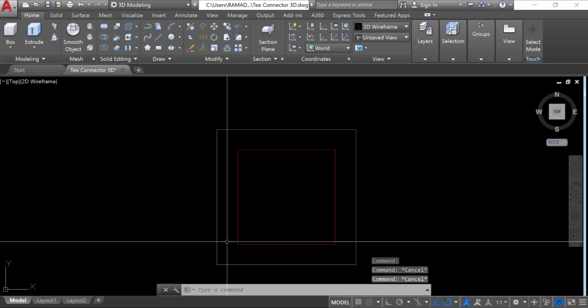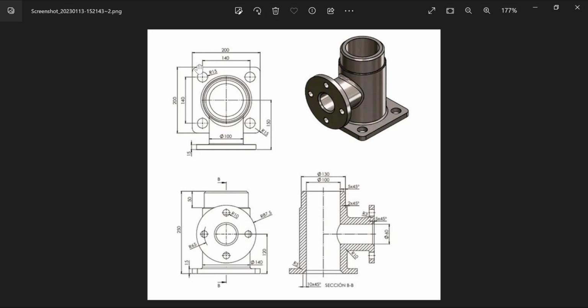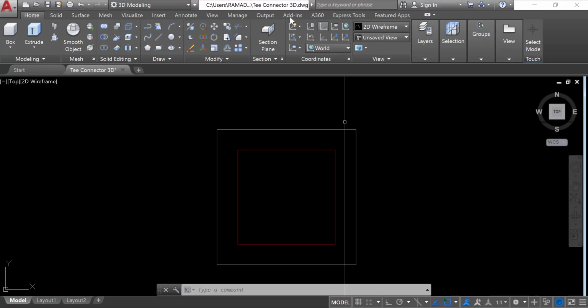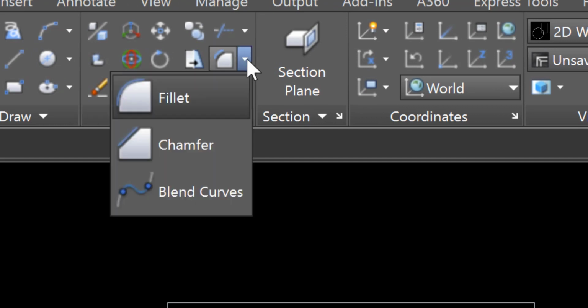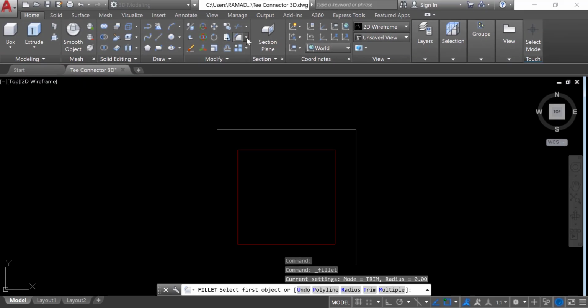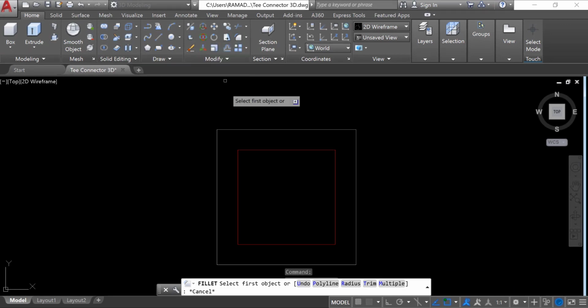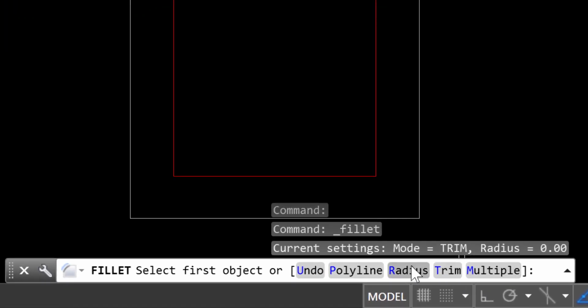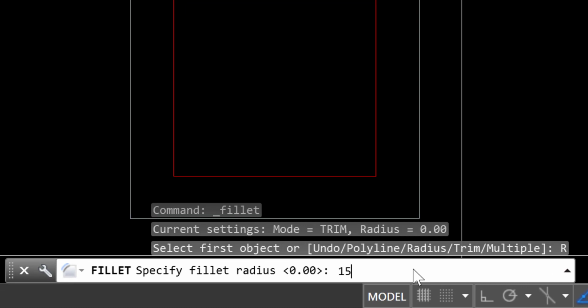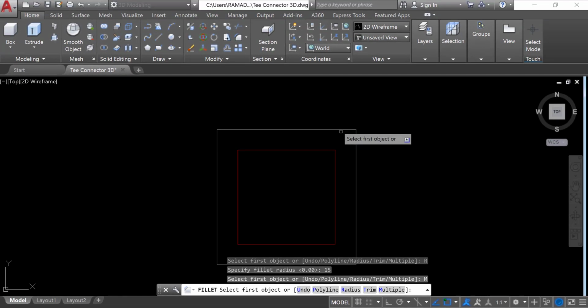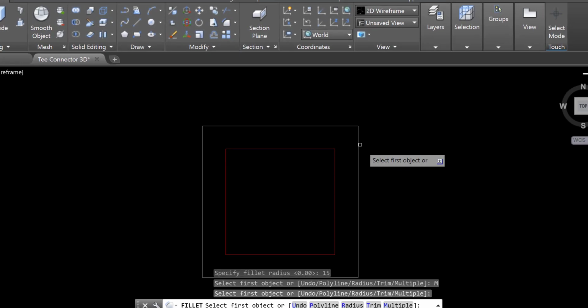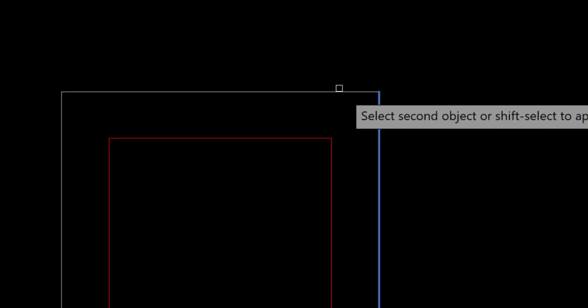Okay, so let's continue. From here, there has been made a fillet round of radius 15. So let's make a fillet. By default, the fillet is reading in radius, so it doesn't make diameters. So the fillet set the radius, which is 15. Press enter and then multiple, because we need to make it on different positions. Let's say this part and this part.